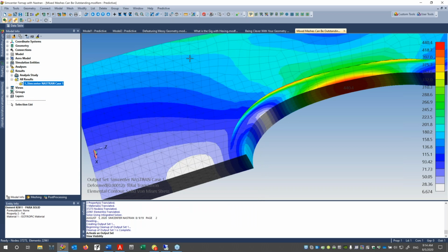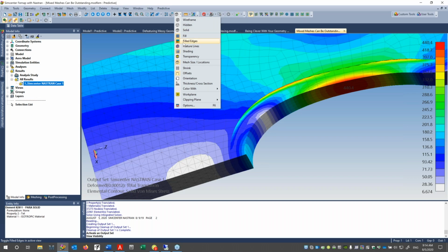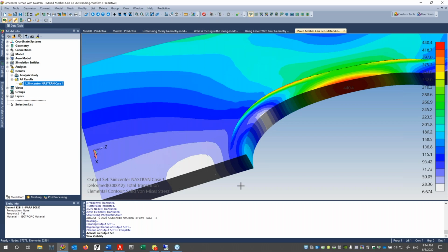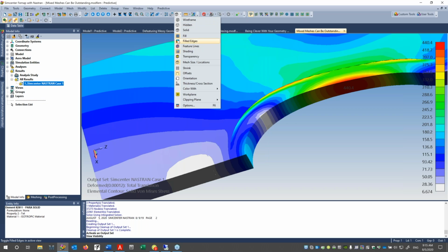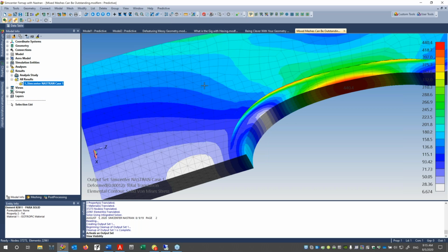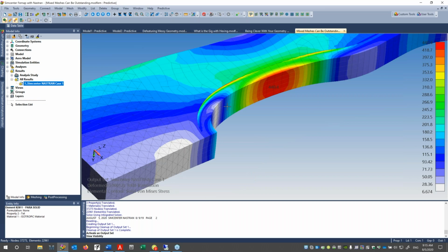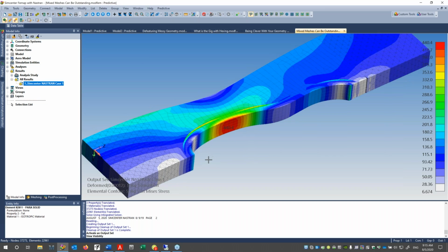Is it smooth? And I think, guys, you've heard this: if you turned off your edge outlines, does it look realistic? Or can you see mesh splotches? So you look at this and you go, yep, that's good enough, and there's no way you could see an interface. If I was really picky, I'd show the same model without the pyramids, with a glued interface, and see if you get the same behavior. But I've really started to use it a lot.